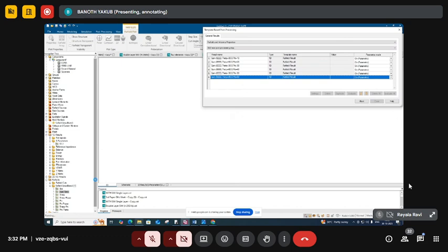For example, 45 degrees, and the phase angles we can change. There are a lot of options, but in a simple way I explained how to check whether the particular bands are matched or not. Theta is 90 degrees and the phase angles we are changing from 10 to 150 degrees. If it does not match, you can go and change the phase angles and theta angles.